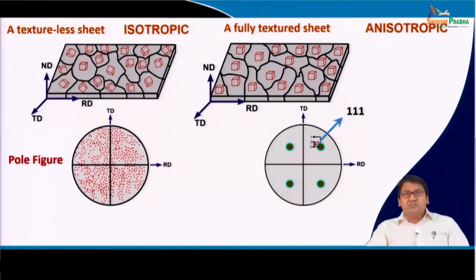So, you see that what I have done is that between each grain I have put the same unit cell schematically to show. Now, if the orientation of adjacent grains is the same, then the boundary between these two grains must not exist, right, because the orientation difference between two adjacent grains will create a misorientation, and only then can it produce a boundary.